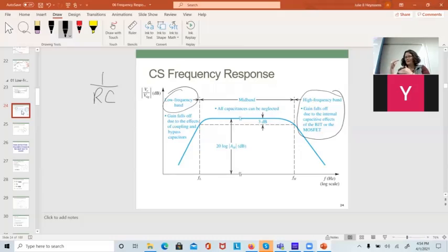And instead of building the gate using a capacitor, they used a reverse bias diode. And they work really well, and they have a really high input resistance. But if you put the voltage on the gate at the wrong value, you forward bias that diode, and they just explode. So you have to be really careful with the gate voltage.